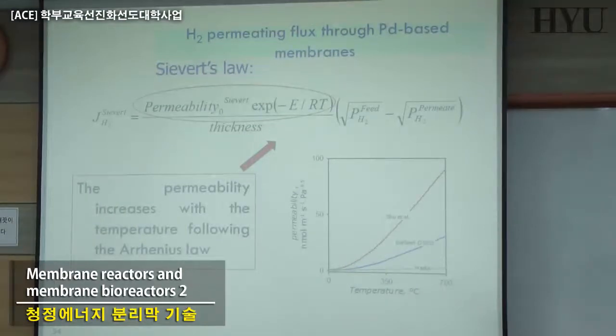Okay? And if you use this kind of equation, you can describe the permeability well in different situations, which is just related to the kind of expression. And for the dependence on temperature, it is the typical Arrhenius law, and that is what you see here. That is the permeability as a function of temperature, and we have a typical activated behavior that is described by this kind of expression.